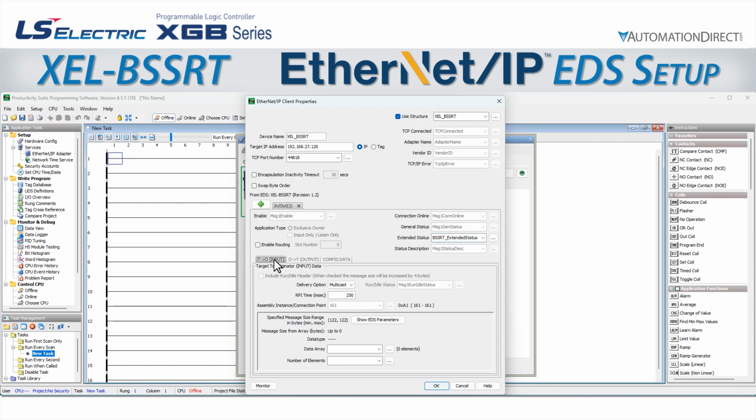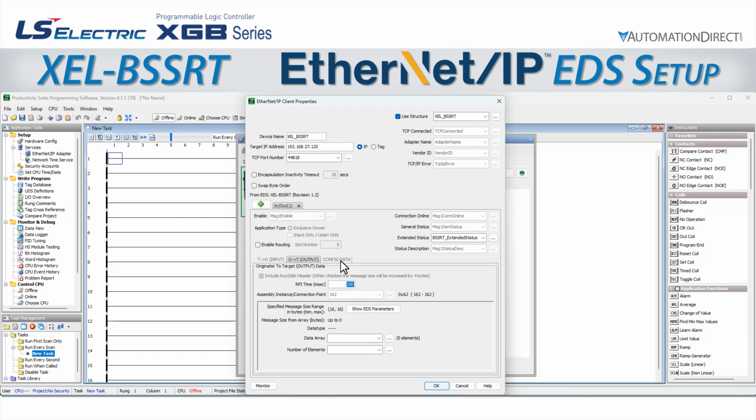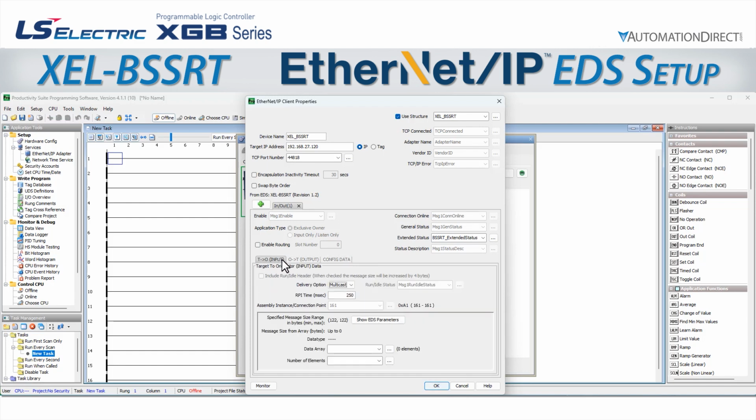For the message itself, we see there are 3 tabs. Since this is an I/O message, there is input data, output data, and config data. On the Input tab, we need to select unicast or multicast, RPI time, and a data array to handle the information transfer. For this example, the Productivity will be the only scanner reading information from the bus coupler, so we will use unicast. Multicast would be used if we had several scanners using listen-only connections to the bus coupler in addition to our exclusive owner connection from the P1550.